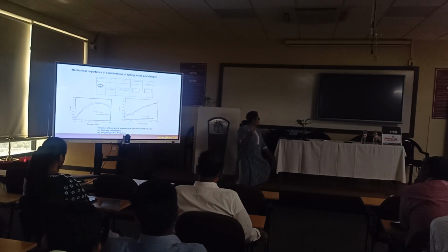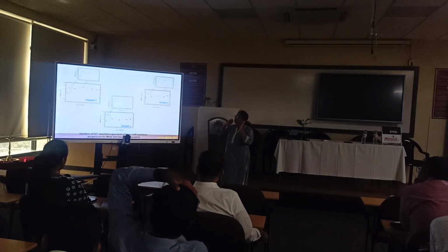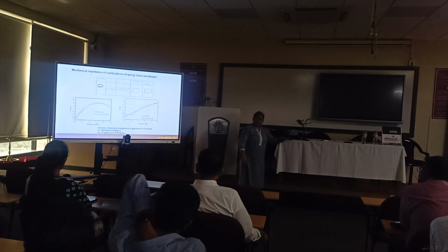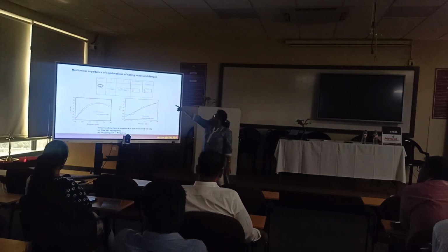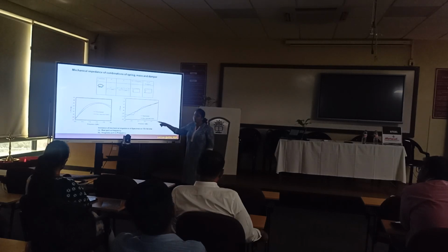With this thought, I didn't calculate everything, I only included the stiffness measurement, because how do we calculate stiffness? I use this particular formula. Y has K, right? So I have a Y in this particular curve, I can have Y0, Y1, Y2, Y3, and I can have corresponding omega 0, omega 2, omega 3 as frequencies, solve it out and find out my K.